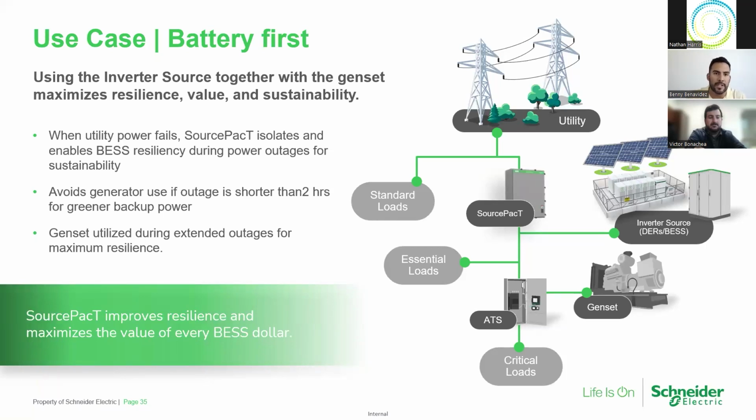It allows for a more sustainable emergency power source where you count on a cleaner energy storage system to come online. And then it gives you the redundancy as well in the generator where you're going battery first. Most outages last a little bit, like an hour, 2 hours tops. But for whatever reason, should that extend beyond the duration of the energy storage system capacity, you have the genset there for an N+1 emergency power scenario.